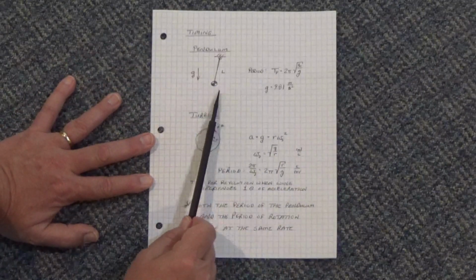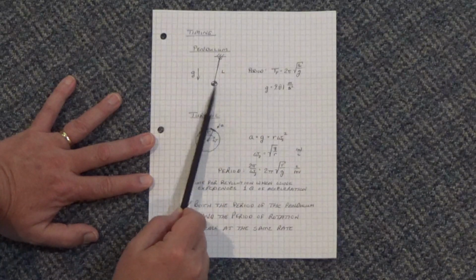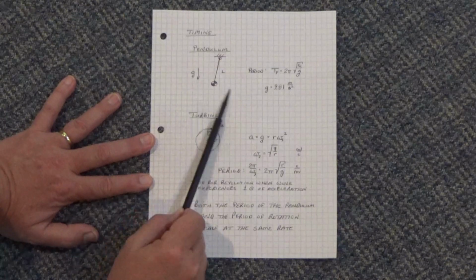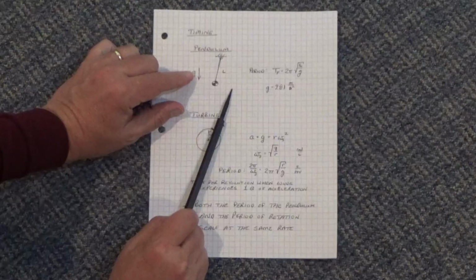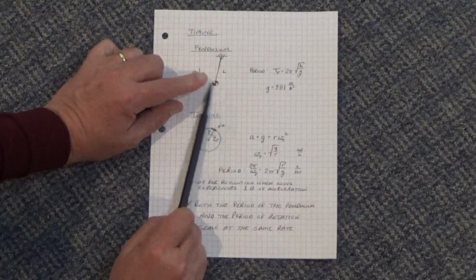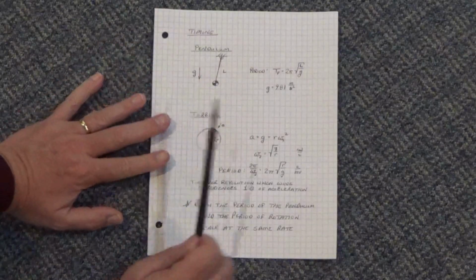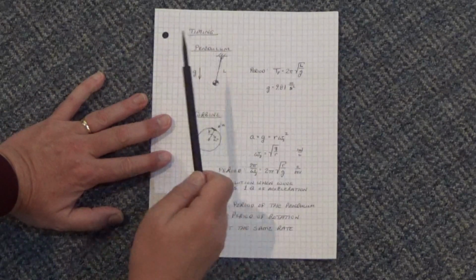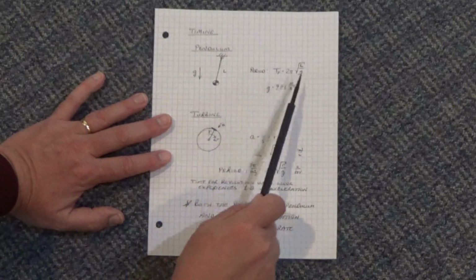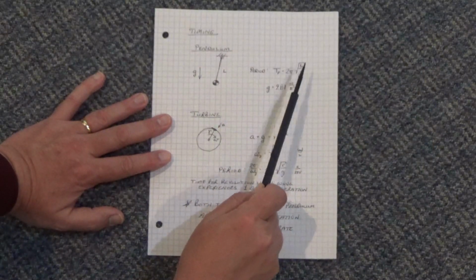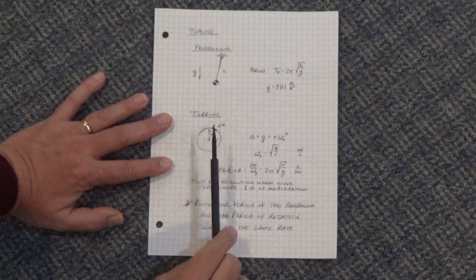But anyhow, this is for a point mass on a string. The wing is not a point mass, it's got some inertia to it. And so if you separate the wing and the counterbalance, you can increase the inertia, and that's going to affect things. But for the most part, it's defined by geometry, and if you keep the geometry the same as you're scaling, it should change with the square root of your length, or whatever you're scaling it.